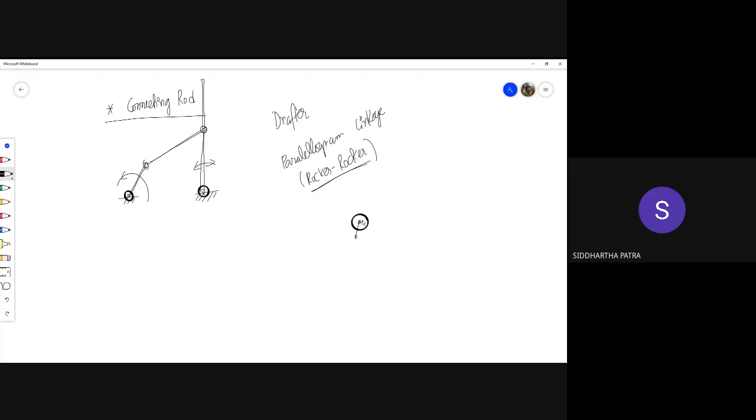So there you have a motor, and that makes the crank rotate, go full circle, because that's how motors operate, right? The shaft rotates completely. So the crank is attached to the shaft, which goes full rotation, and then there is this rocker, which is basically your wiper, and that just oscillates while this goes full rotation, and this basically wipes the glass of the windscreen of the bus. Okay.